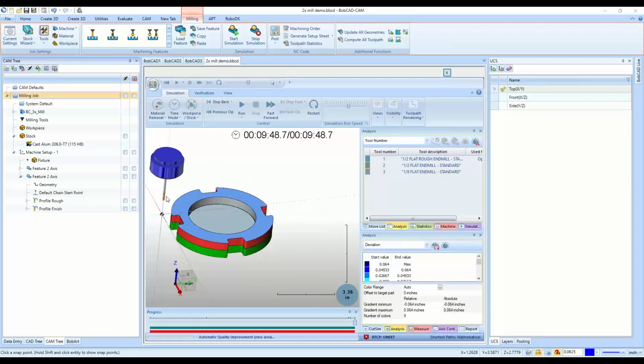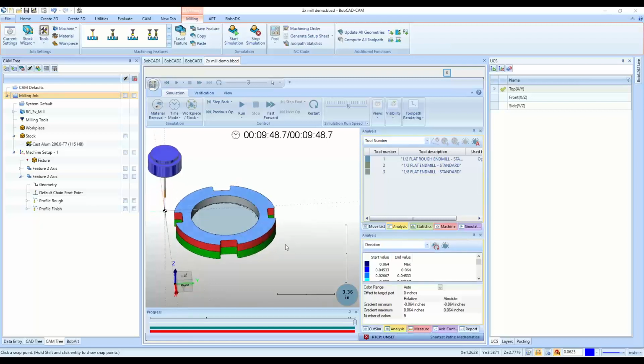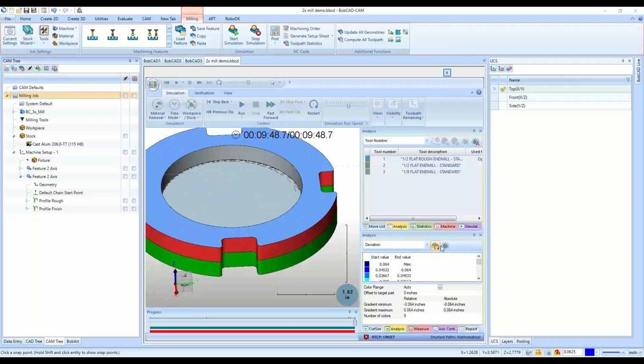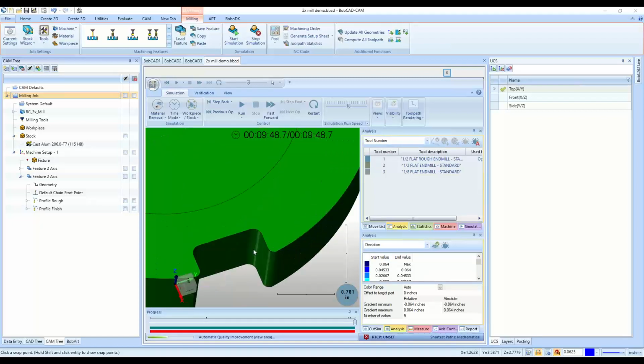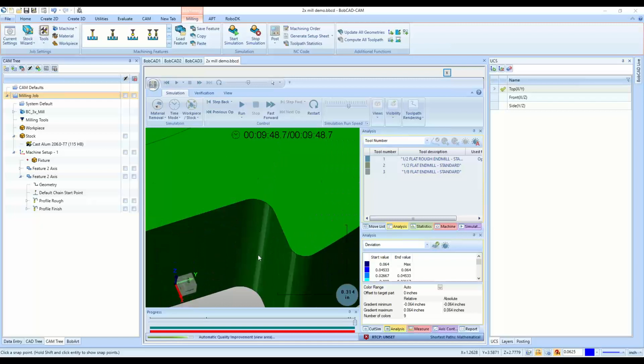We'll just assume right now that tool has a cutting area a little bit taller than what that was. We'll refresh this deviation report. Should get rid of that red for us. And we'll want to look in the corners and see the specific colors in the corners. Make sure there's no blue in the corners. Everything is cut to size from what I was trying to make with our finished 3D part. So everything is cut to size.